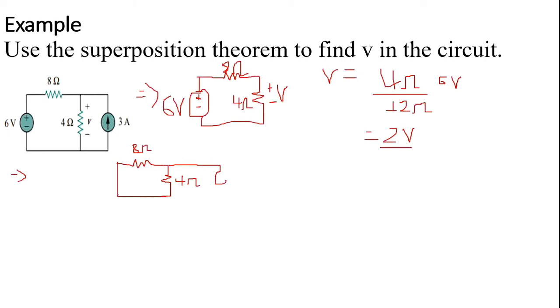And we have a current source here, which is 3 ampere. Now we can use either mesh analysis or nodal analysis to obtain the voltage drop across this resistance. But instead of using nodal or mesh analysis, we can use the current division principle for simplicity.